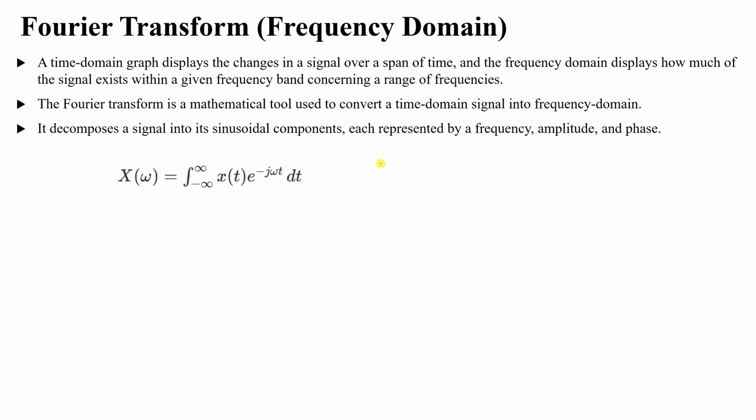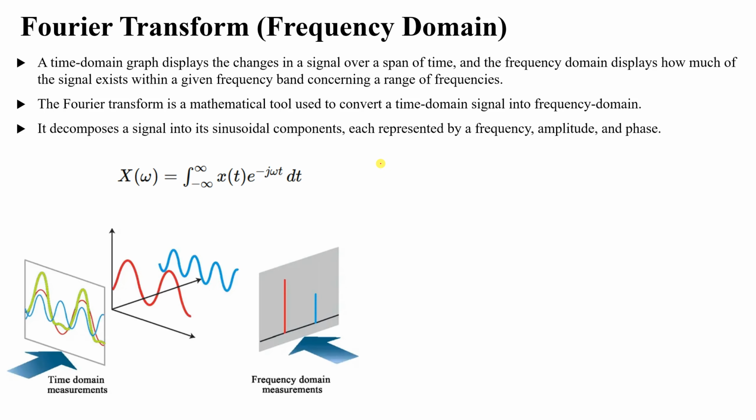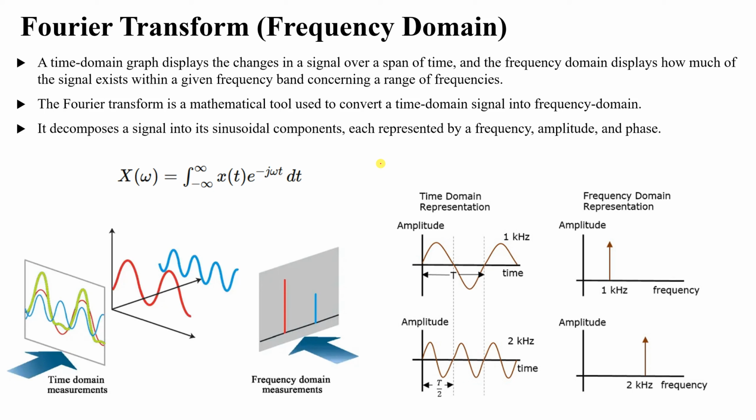Now you will say, why do we even do this? Why do we use Fourier transform for non-periodic signal? So exactly as we did before, you can see we transformed a signal like this into frequency domain using a Fourier transform. You can see using Fourier transform or Fourier series. Fourier transform if it is non-periodic, Fourier series if it is periodic. Like this here, you can see it has a certain amplitude and frequency, 1 kilohertz, frequency, amplitude, frequency, and amplitude.